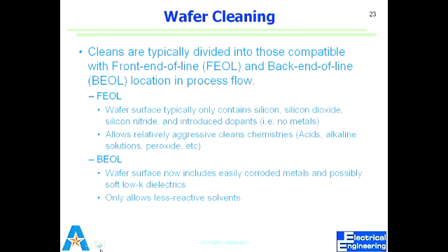All right. How do we clean wafers? Let's start with tweezers. How would we clean tweezers? Get a new tweezer. What should I do to get rid of anything? We start with something called solvent clean. Now, solvent is simply stated something that can dissolve other things, right? So solvent in this case we consider as non-acidic, non-basic solutions. What are those solutions which are not acids, not bases? Acetone, alcohol. So acetone is a very good cleaner, very good solvent.